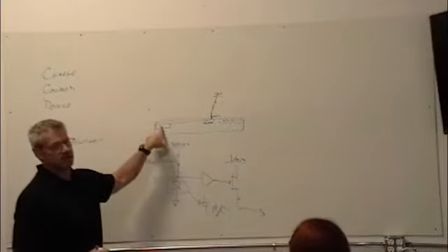So this one will trap an electron for a little bit, and then sometime later he'll release it, and you'll get false readings. You'll say, oh, that electron happened here, but no, really it happened over there. There's no way to know. And you can do a bunch of statistics on the stuff, and you can realize that, over 5,000 pictures that are just a plain white field, you can say, oh, it looks like I've got an electron trap there, or a couple of them, and there's a propensity for them to happen, but you still don't know, because it's a statistical process. And given any one image to the next, you don't know which one's lost that. There's image processing things you can do to help get rid of it, but it's an issue.